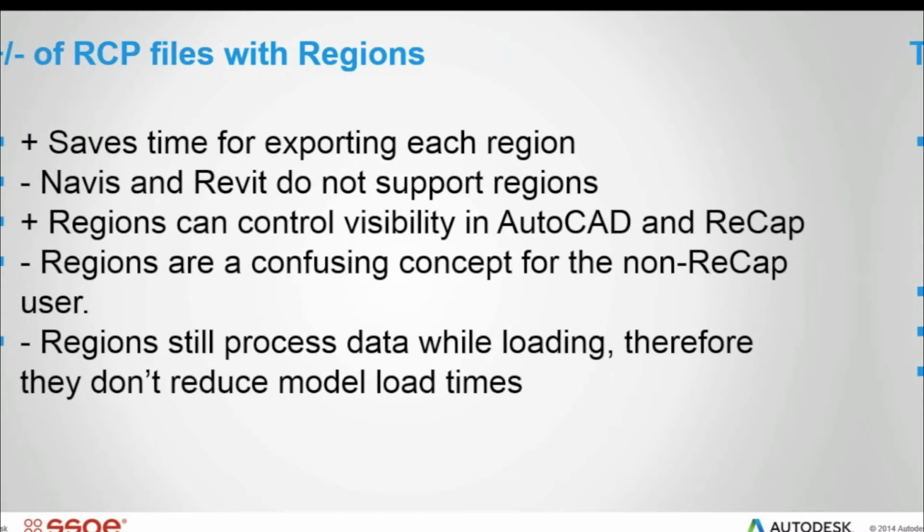Also, a point of note, for those of us in ReCap all the time, regions make sense. We understand what they are. They're like layers in AutoCAD or work sets in Revit. But for people that don't use ReCap, your modeling folk or anybody else, they don't know what a region means. It's just another education point, another point of confusion. So if you just take the time to export the files, it's a lot easier for them to understand. Turn the file off, everything's off, rather than going inside the file and turning off the specific regions.